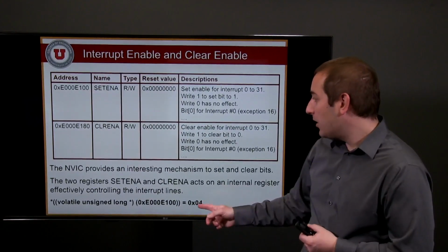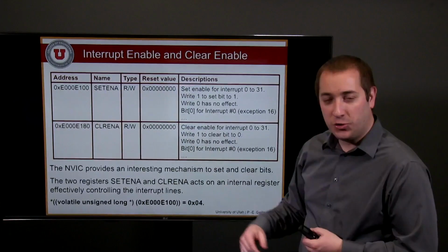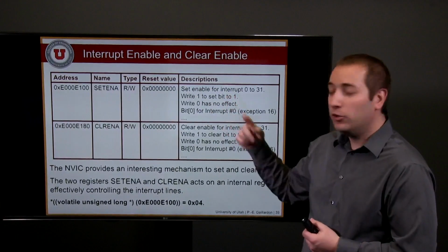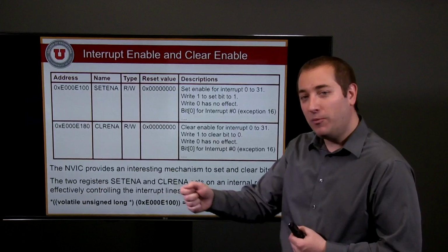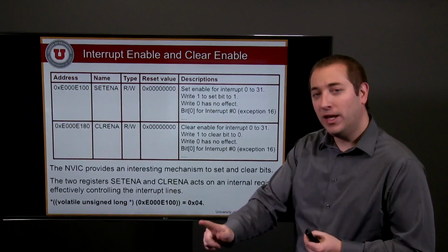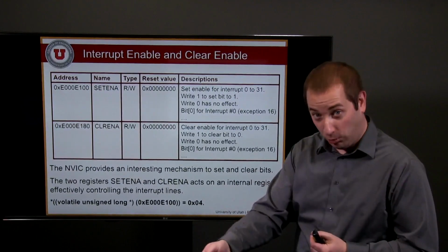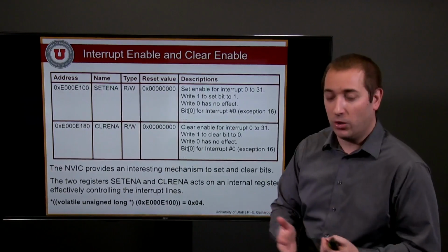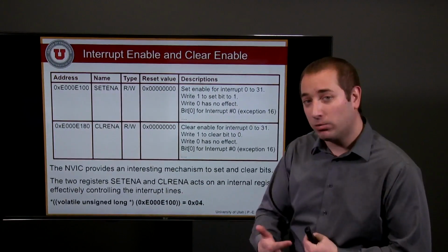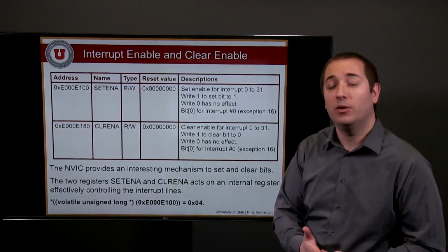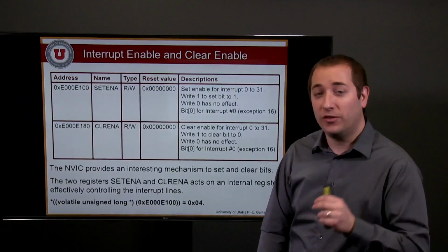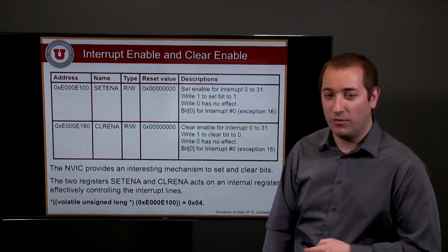And well, it turns out that the way this register works is that you write a 1 into, for example, this register to set the bit to 1, and once this bit will have been set to 1, it's going to be going back to 0. So you write something, but then the processor automatically clears up what you wrote in order to somehow acknowledge that it was done properly. So this register is going to change in the background. This is not something you do control by your software. So this is why you have this volatile keyword to let your compiler know that someone else than him might actually impact the values.